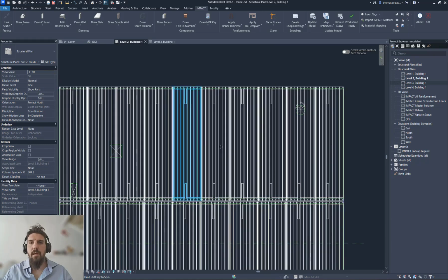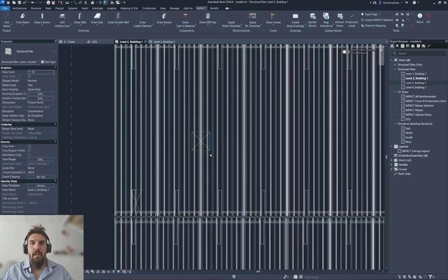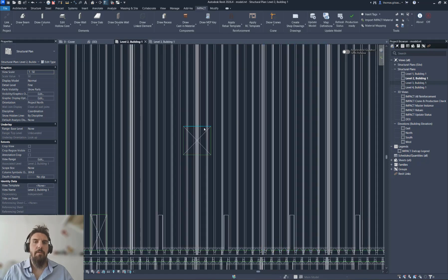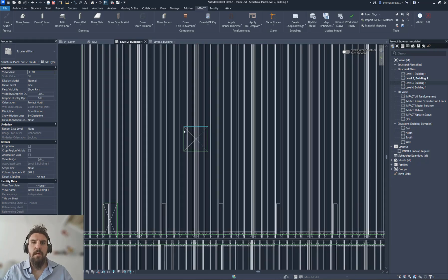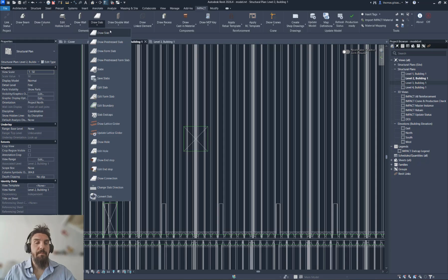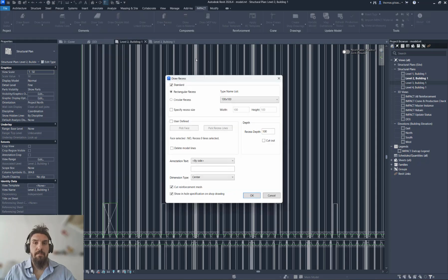It is correctly made. In the same manner, we are going to do this, but here this is added in 2 slabs. And that means that in Revit, in order for this to be achievable, we will need to draw the slab, draw the recess, user-defined, pick face again.